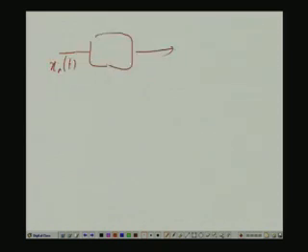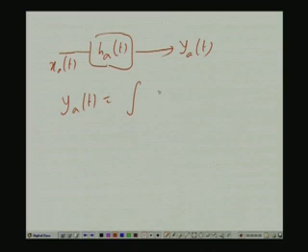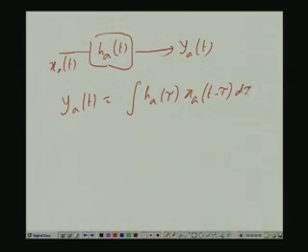That is what we do now: we have got a process X_A(t), it is input to our analog system h_A(t), this is the impulse response. Once again I put a subscript A here to indicate it is an analog system. The output is a random process Y_A(t). Y_A(t) is given by the analog convolution between these two, X_A(t) and h_A(t), we all know. So, this is Y_A(t), which you can write either way, maybe you write this way: the integral of h_A(tau) X_A(t minus tau) d tau from minus infinity to infinity.